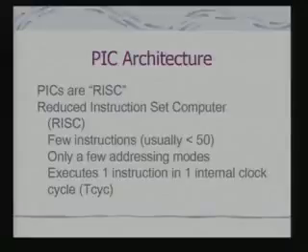In fact, the basic objective with which PIC microcontrollers were designed was embedded control. PICs are RISC processors, reduced instruction set processors. They use fewer instructions, a few addressing modes, and typically execute one instruction in one internal clock cycle.